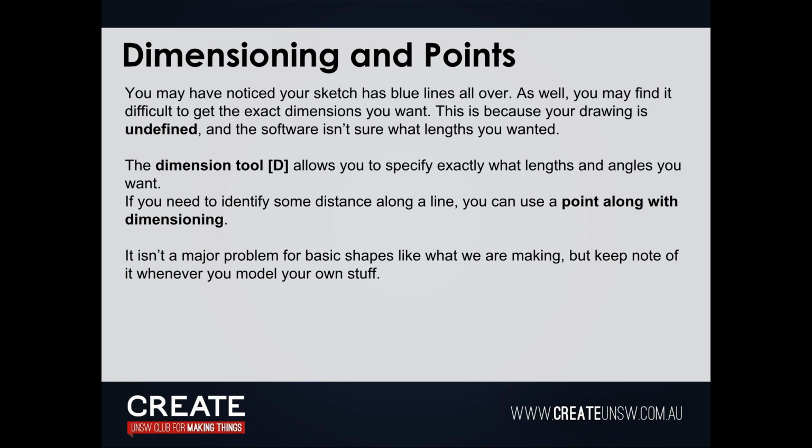So for example, if I want to change the values right now, just for some of you that might have missed it, right click, edit sketch, and you can see the dimensions there, 500, 250. You can click on these dimensions. If you can't see the dimensions, you can do sketch dimension.